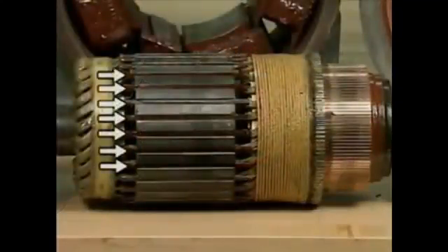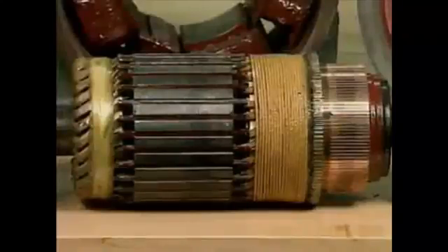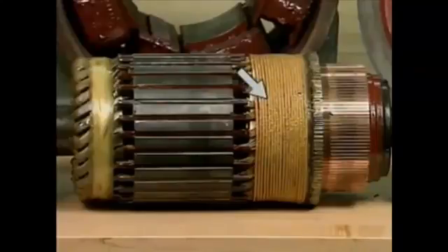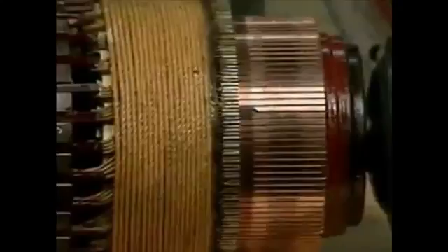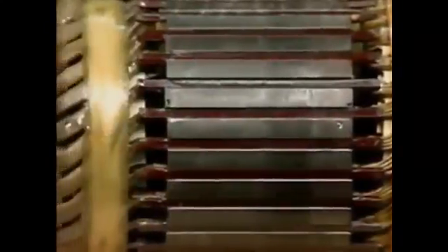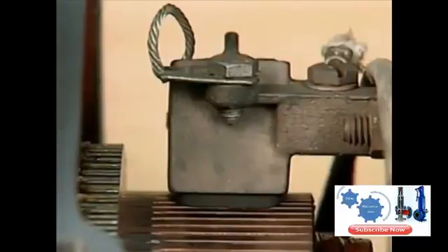The armature contains several loops of wire that are wound back and forth. All of the loops make an electrical connection to the motor's commutator segments. The electrical connections to the commutator segments are protected and held in place under a wrapping of varnish-coated fibers. Current flows from one commutator segment through the armature and back through another commutator segment. The commutator makes sliding contact with a set of brushes. The brushes, which fit in holders, are held against the commutator by springs to maintain contact and to provide a path for current flow from the power source to the commutator.